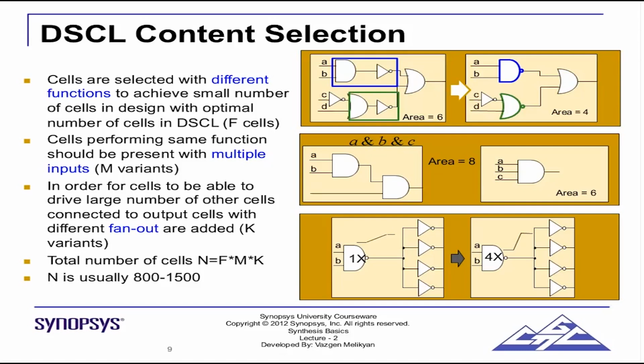First rule is that apart from the minimal function set, that is AND or NOT, NAND and NOR, there should be a lot of complex functions also to make sure the design is optimal. For example, you would come across muxes. Now, if we go back and revisit unit 1 and 2, you will see that a mux design is much more area efficient when done with transmission gates as compared to normal CMOS logic.